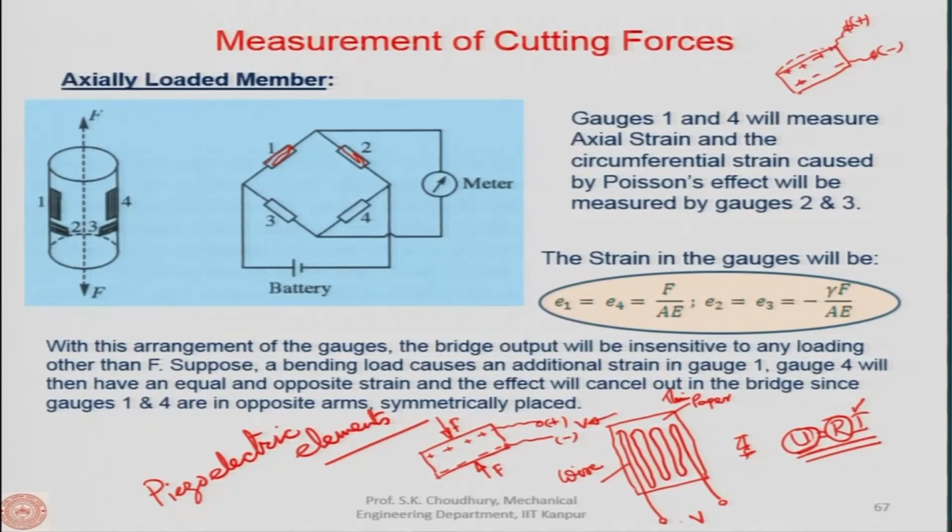I am exaggerating, of course, it will not expand so much. And if you remove the voltage, it will come back to the initial position. So this is the direct piezo effect, and this is the indirect piezo effect of the piezo elements.